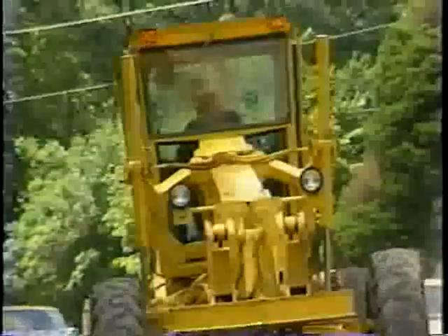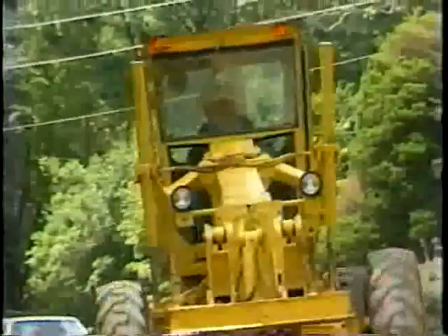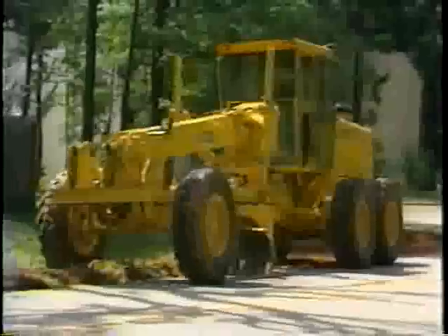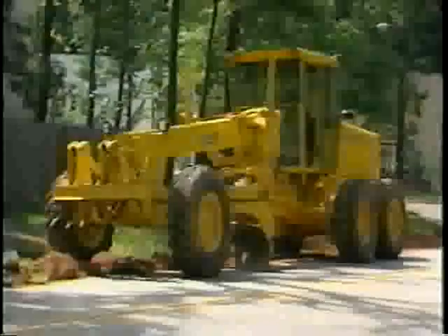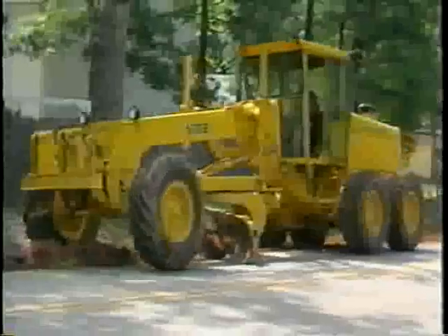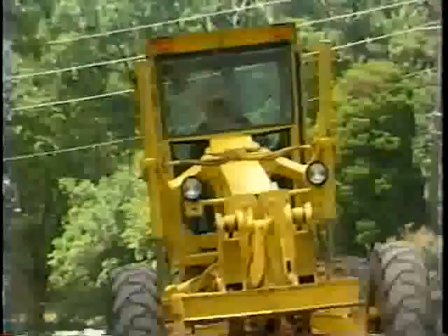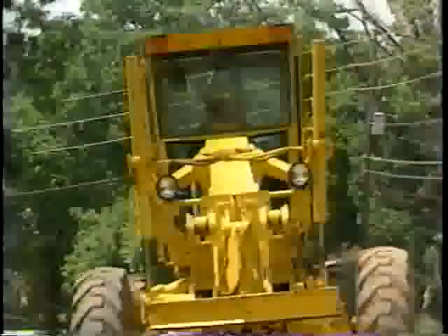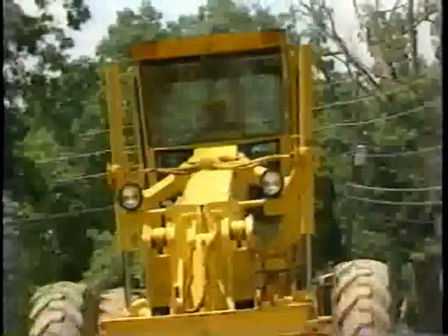Use a front wheel lean of 10 to 15 degrees in the direction that material is being moved. Operating speed is relatively slow, about 3 to 5 miles per hour. This prevents the blade from bouncing and creating an unevenness in the finished shoulder. The reshaped shoulder is flush with the edge of the pavement. Take care not to cut into the pavement with the edge of the blade. Depending upon the width of the unpaved shoulder, additional passes may be needed to reshape the unpaved shoulder area.